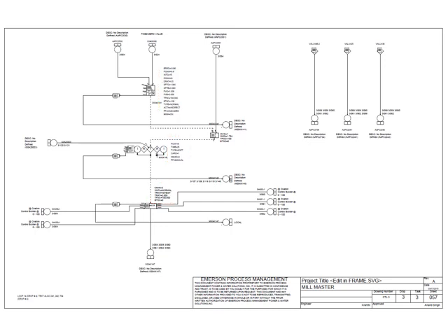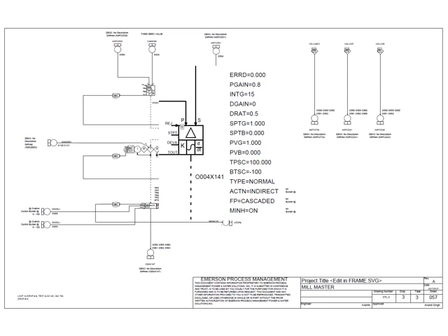Okay, this is a PID controller, but in this case, it is a proportional integral controller only. Why do I say so? The derivative is set to 0, meaning there's no derivative action. If you may notice, the set point is set to 0, but the action is indirect, meaning the output should always be at maximum. And then the process variable came from sheet 3.3.054, and it is a computation from both fuels.